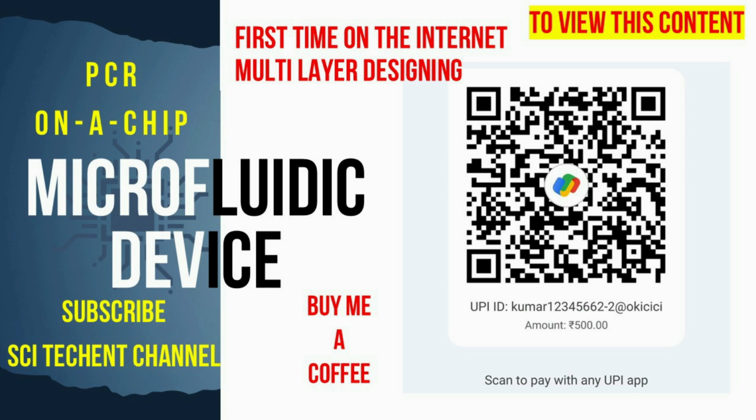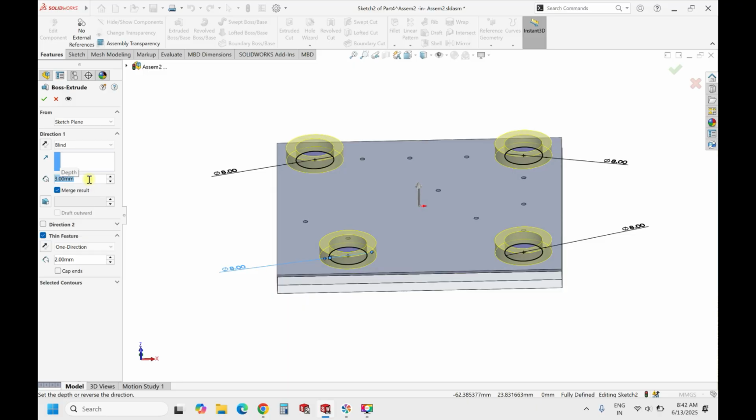So once this is done, go to features, extrude, and now this time when you're extruding, don't use this solid option, just make a thin feature and keep it to 2 mm wall thickness. Okay, and then we can make it somewhere around 3 mm in height, 3 or 2 mm, whatever is feasible, or even 5 mm. So basically this is to pour the liquid, so we can keep it as 5 mm.